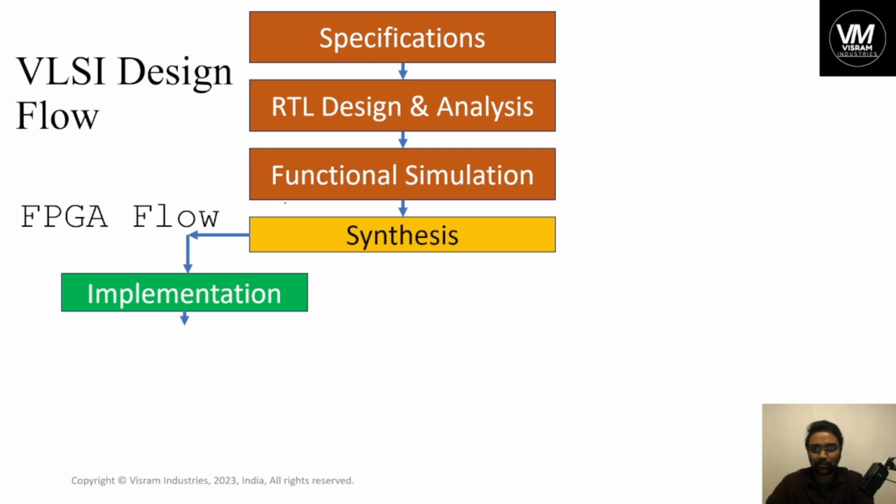At this, near the port or center of the port, the clock can be sitting in the center of the design for easily connecting with all the logic cells, and output ports communicating with some of the blocks or registers near the output port. So that automation will be done using the EDA automation tool. Implementation is done. So placement and routing are the major steps in implementation.